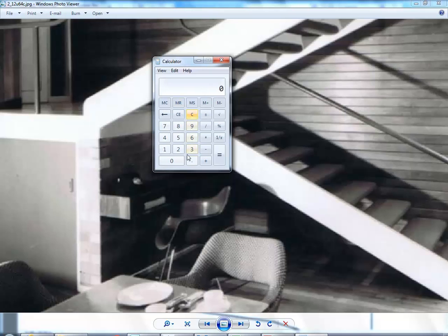And okay, so 86 times, what did I say, 14? Yep. So that gives us 1200. And the tread height that I gave was a little bit more than that, and we've got obviously the slab there and the bit of skirting. So it wasn't far off. I think that's a good measurement.